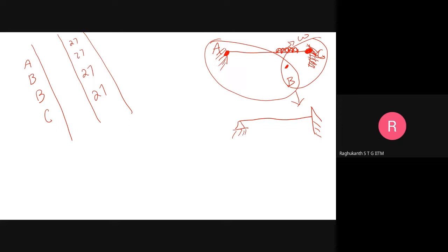Now still it can take the load. Let us say a hinge forms at this place. Now this propped cantilever becomes once again a simply supported beam itself. Once again the hinge has to form at another place for this beam to collapse. So you will have stage one, stage two, stage three analysis. Once the hinges have formed, it will lead to collapse. So this is a straightforward procedure. If you are writing it on a computer, it is very easy to calculate these things.